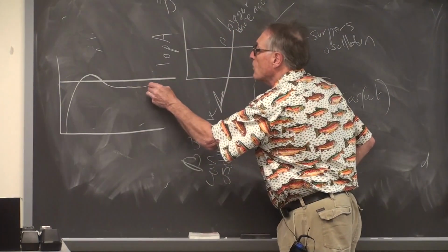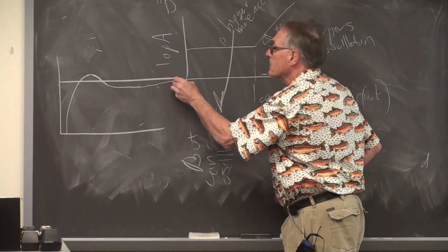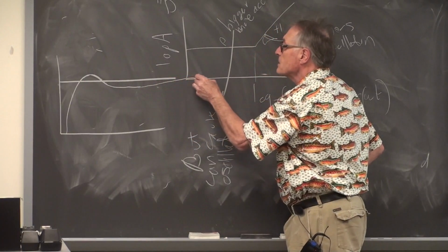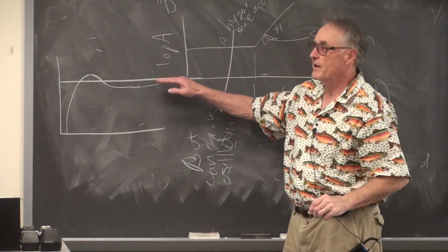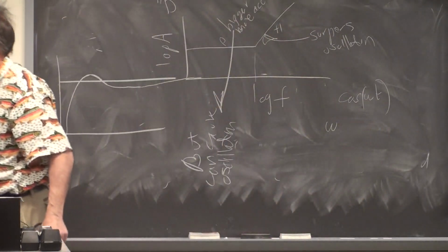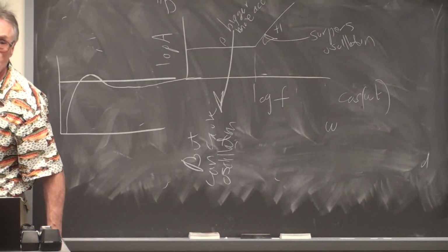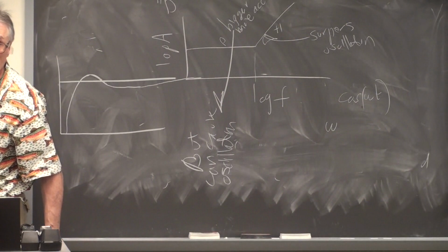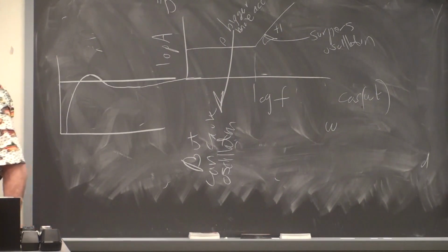You want it to slowly creep up as the integral term gets bigger and bigger, and creep up towards the final desired value. So you want this term to be the creep up to the final position term. So, high gain, highest possible.